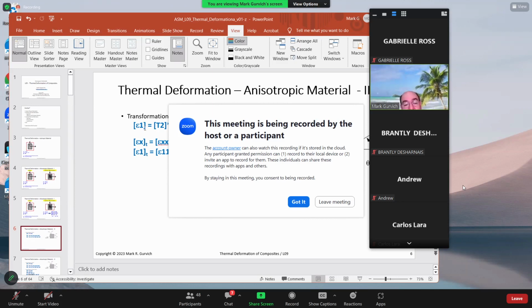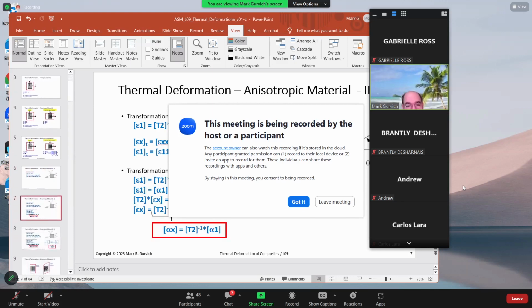And in the general case, this matrix could have size 6 by 6, and if we consider a simpler two-dimensional case, like in-plane, it will be reduced to a 3 by 3 matrix. So again, exactly the same as what you had with analysis of stiffness in different coordinate systems. So this so far has nothing to do with thermal expansion. But the next step, let me add here, shows how we can relatively easily calculate thermal expansion in any other orientations, in this case X and Y.